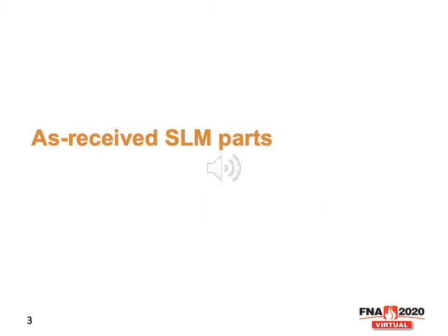In the following slides, I'm going to show the characterization work we've done on SLM parts, selective laser melted parts: chemistry analysis, Vickers microhardness line scan, optical microstructure analysis, SEM microstructure analysis, and XRD analysis on the sample. Also the porosity analysis on this part.